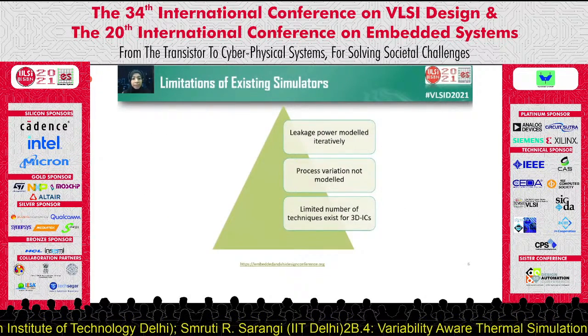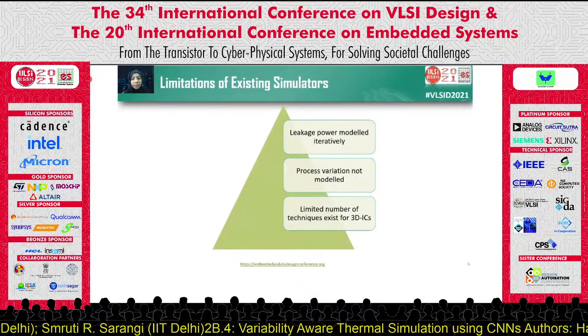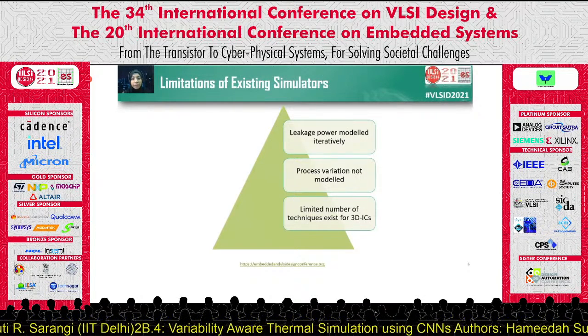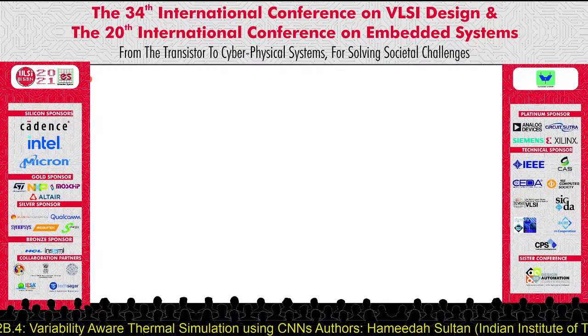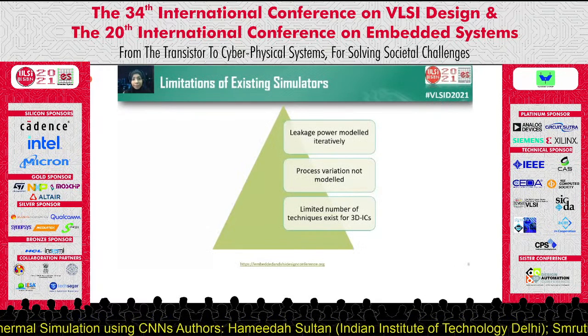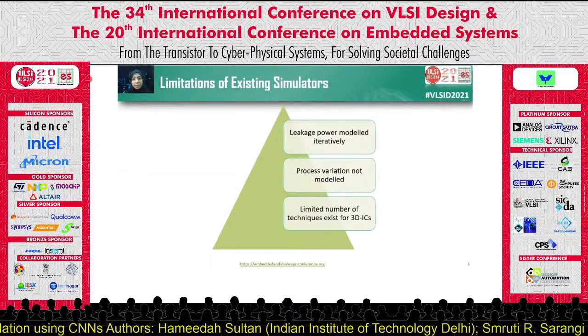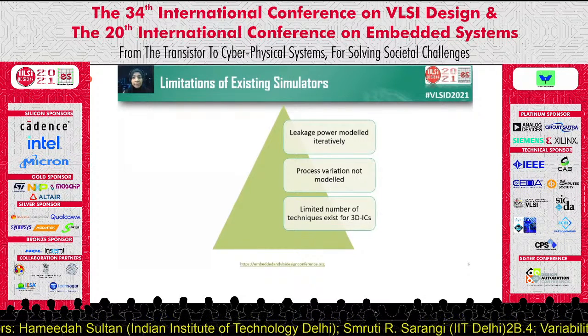Now, there are several limitations of existing thermal simulators, which led us to explore another thermal simulator. The first is that most state-of-the-art methods model leakage iteratively. This increases the runtime by at least 3 to 5x, since at least that many iterations are needed for convergence. This makes the existing simulators very slow.